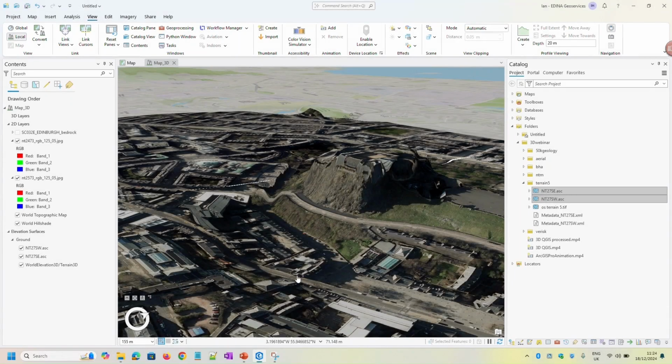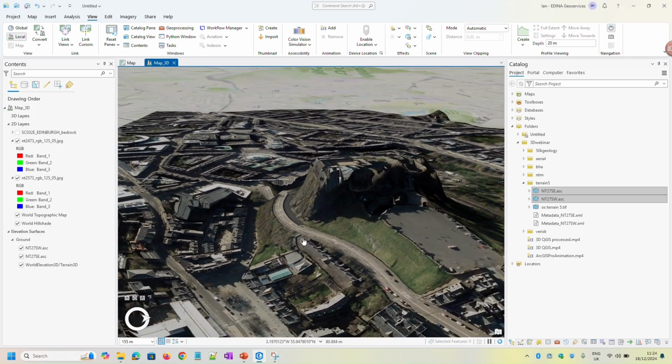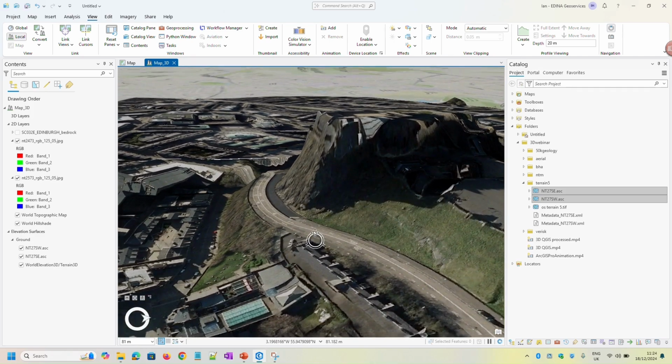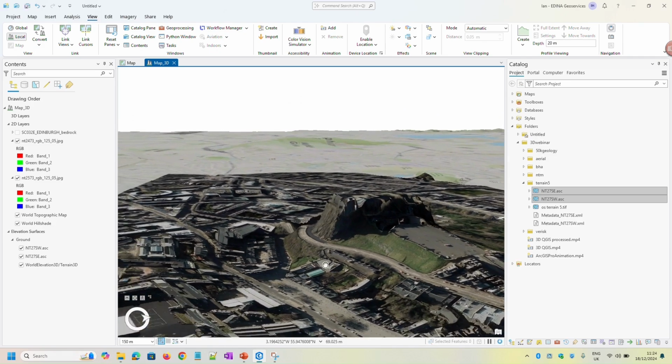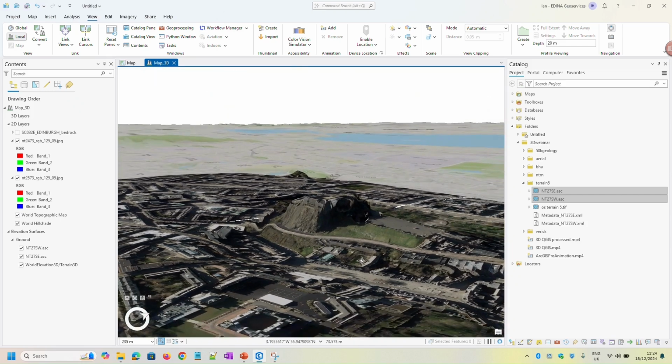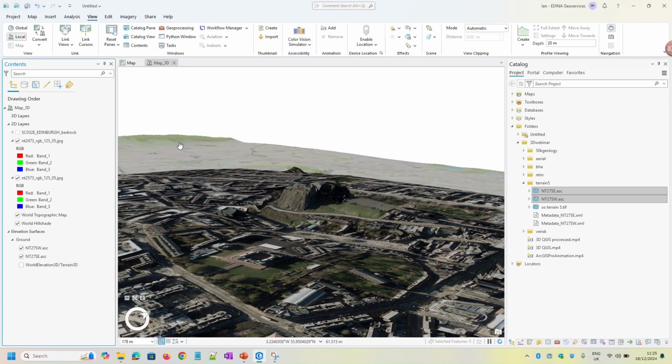Okay, now that's finished displaying, we can see that if we zoom around and have a look at the road now, we've actually got a much more detailed terrain surface here. The road is being displayed horizontally, and this is now using the OS Terrain 5 data that's been downloaded from Digimap. So we can turn off this world elevation layer here, and it'll just speed up processing, so you'll see the terrain in the distance disappears. It's no longer rendered.